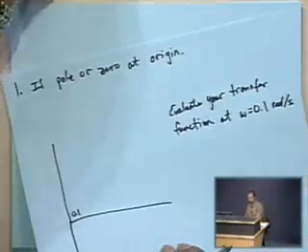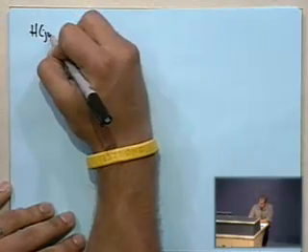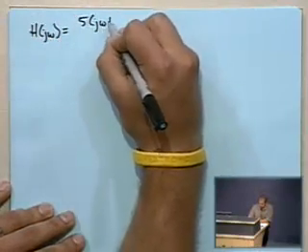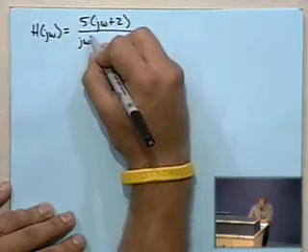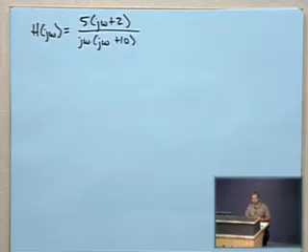So, in the way of a brief example of at least the somewhat harder one, consider a transfer function like, let's see which one I want to do here. Let's do this one. So we've got here H of j omega equals 5 times (j omega plus 2) over j omega times (j omega plus 10). So there's our transfer function. It's not in its proper standard form, and so figuring out what the k0 term is going to be is actually going to be determined by, well, we have to put it into standard form.